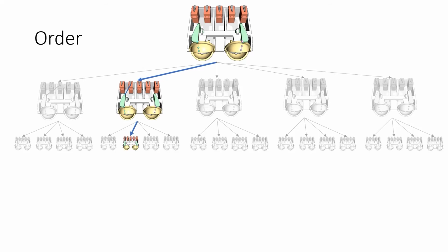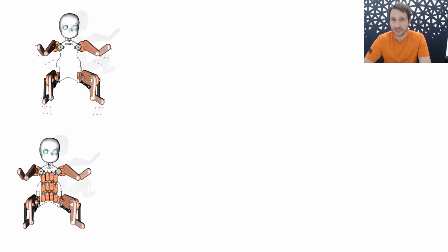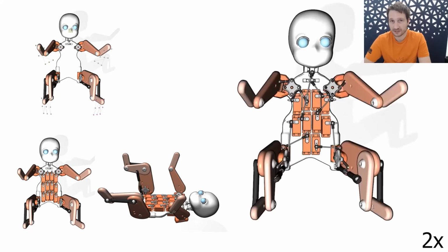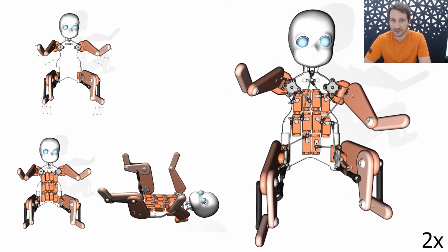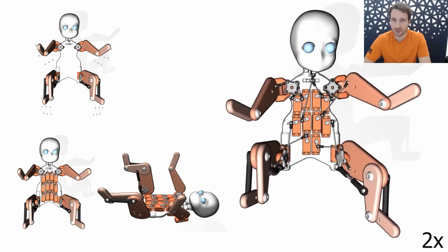And now, let's see some results. First, let's start with a baby model with 10 degrees of freedom and 24 possible motor positions to choose from. The motors are stacked in two overlapping layers, each with 12 motors, to accommodate for multiple motors intersecting. We just don't create a child node in the tree if the parent and child node would intersect with each other.